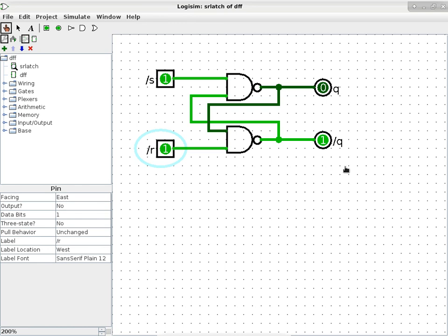So by pure luck, your circuitry may not exhibit any problem. But later on, when you change the die size and the transistor size, it may change the timing, and then your race condition will start to show up. In other words, by shrinking the size of your transistors, which is going to happen, the problem may show up one day. And then you'll be scratching your head and go like, I wonder what happened to my design, because it used to work and now it's not working anymore. I didn't change a single thing. It's because this problem was masked by the manufacturing fabrication process. So how do you think I knew about these things?